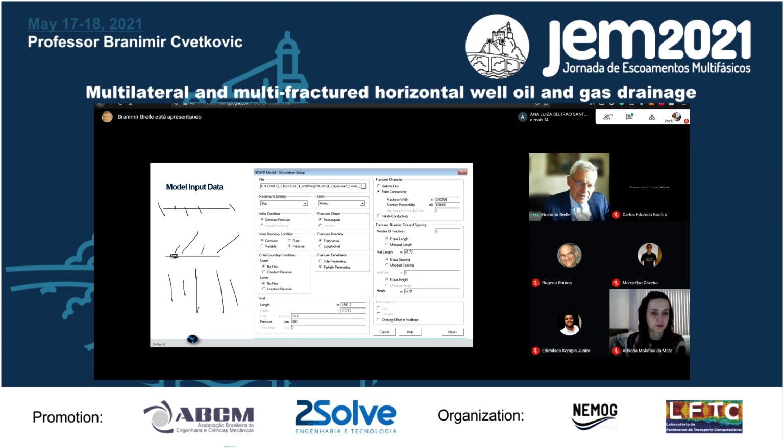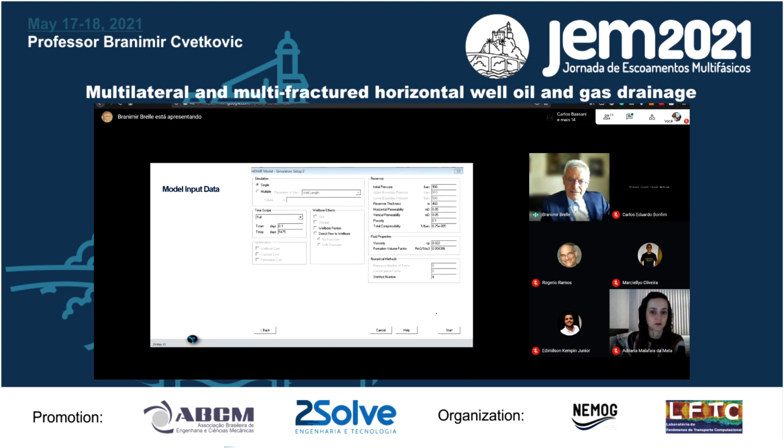We talked about how I can include this extra pressure drop due to the choking. This is here. And then I can have here a full-time solution, or I can have an early time solution, depending on whether you want to move to well testing, or a late time solution. Then I can include wellbore friction in addition to that, because we know that when I have very many fractures, this friction is very dominant. So this profile is not equal, as we saw there. You remember that we have a drawing here.